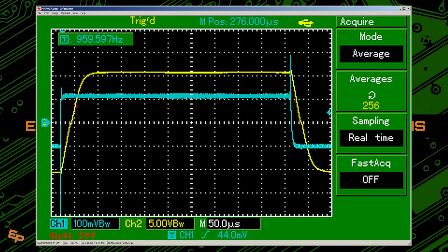And we see with yellow the output signal, and we see that both signals are synchronized with each other. So when the blue, the input signal, starts to rise quickly from minus 100 to plus 100 millivolts, that's when the output signal starts to increase as well. It doesn't increase anywhere near as fast because there's another parameter limiting the op-amp, which is the slew rate. I'm not going to be talking about that, that's a different topic.